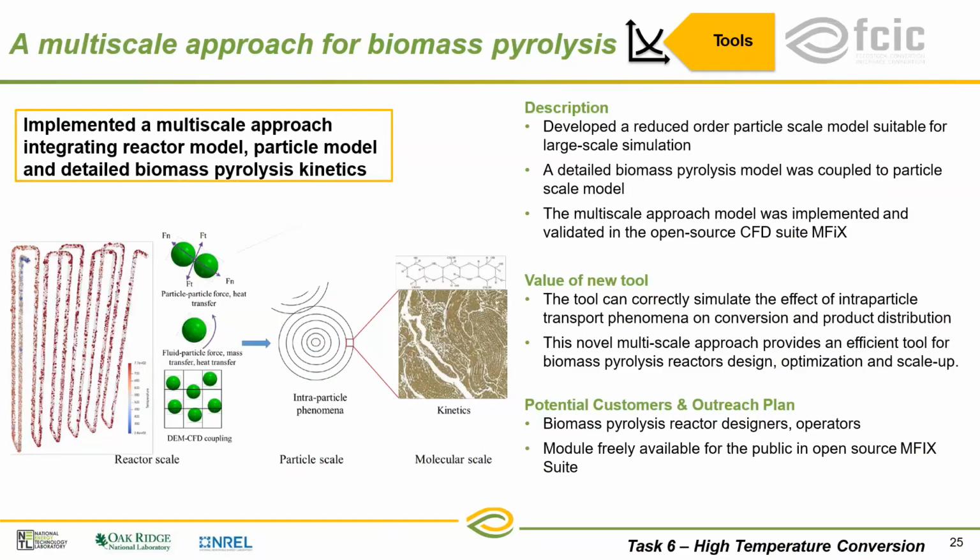So the researchers developed what is called a reduced order particle scale model that could then be taken into the reactor scale modeling. So it's still faithful, if you will, to the lower scale modeling work, but now can be used in these larger scale reactor scale models. And this was implemented and validated in the open source CFD suite MFIX, which is available from our colleagues at the National Energy Technology Laboratory, NETL. And again, this module is freely available in the open source MFIX suite.